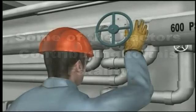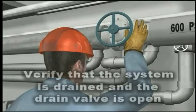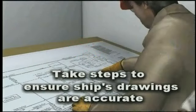Let's take a look at some of the contributing factors that led to this fatality. Use a thermal gun or carefully place your hand near both sides of the valve to check the temperature. Verify that the steam system is drained and the drain valve is open. Be careful not to touch the pipes or valve too quickly. Approach them slowly to feel if heat is radiating from them first. If they are very hot, then they may still contain steam under pressure. Accurate drawings free from discrepancies are essential for effective energy isolation.